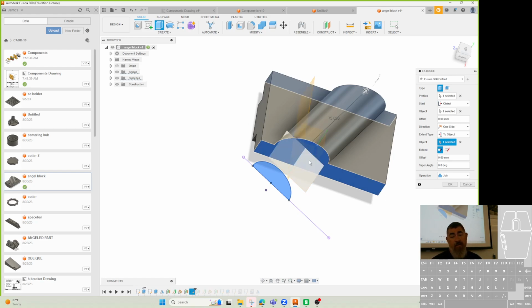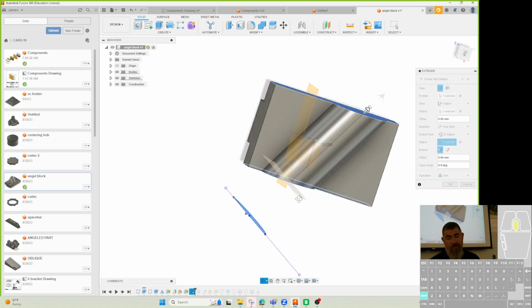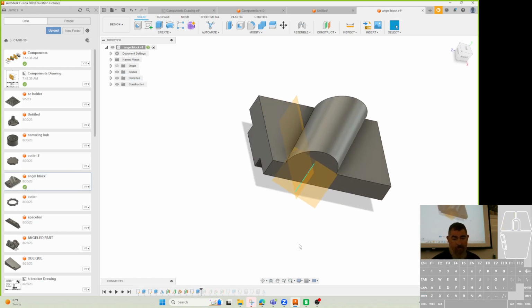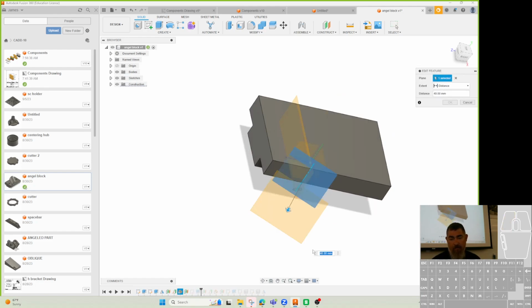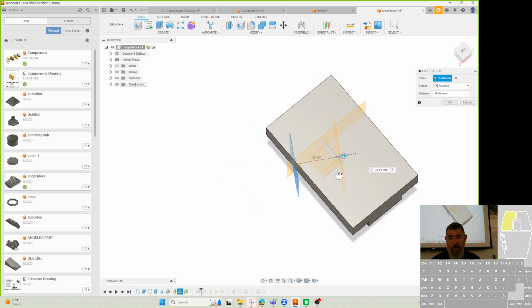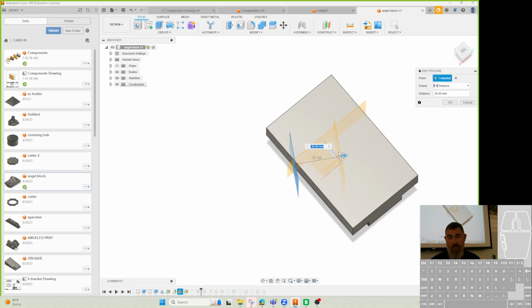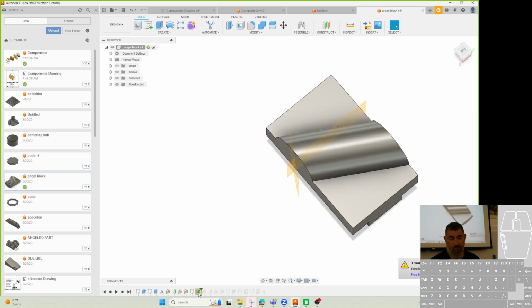Yeah, because this one's cutting through the surface, and so it can't work. It has to be out past the surface. So it could have been here, or it could have been in here. If I made that plane in the middle of the part instead of bringing it out here, same thing, it works. It just doesn't work if it's touching the edge. Oh, so now it broke.